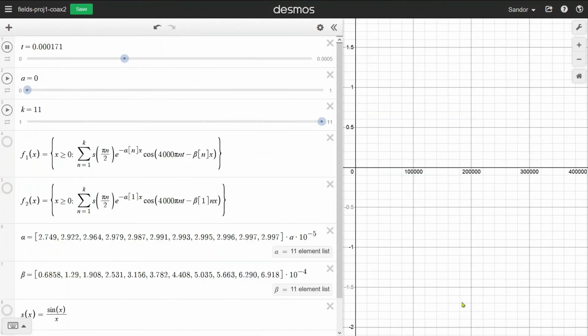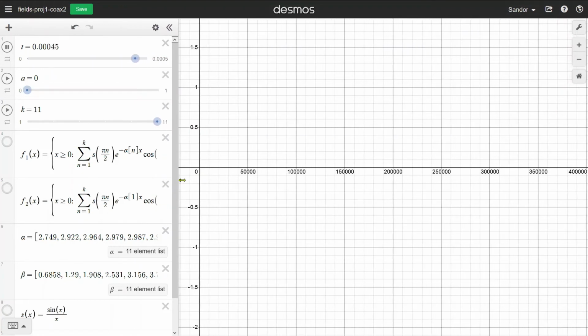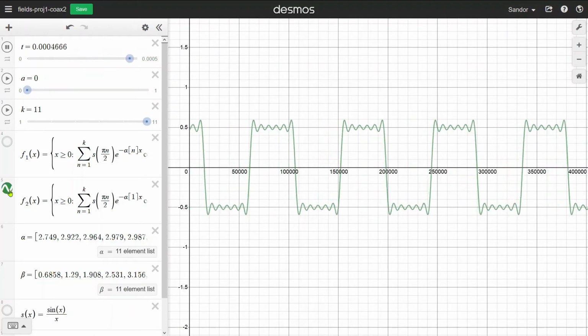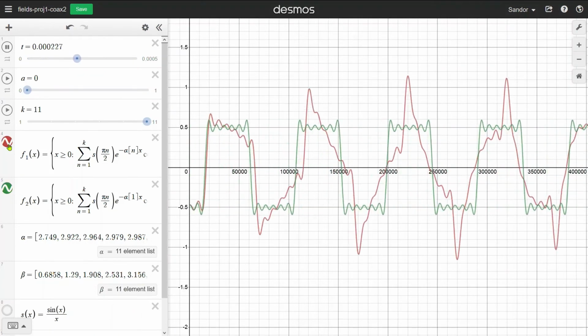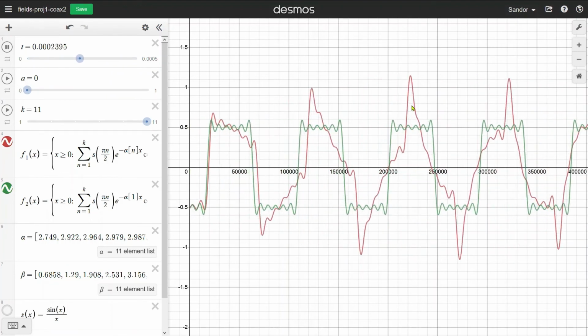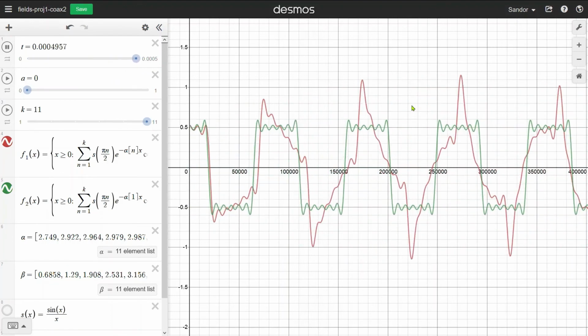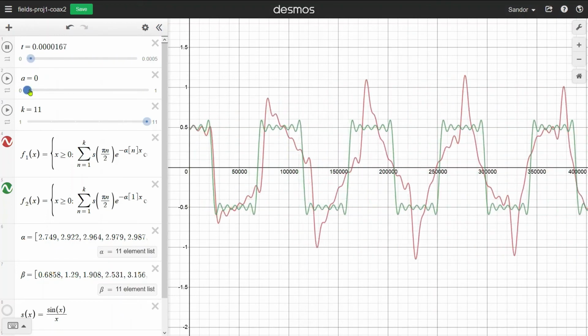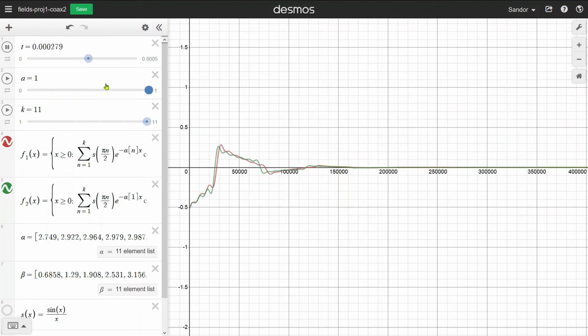The same can be seen for this 2 kHz square wave approximated by the first 6 non-zero terms of its Fourier series. Let's assume there's no attenuation for the moment. Here's what we should see, and here's what we actually see. Notice how the general high to low pattern of the pulses remains the same, but the higher frequency oscillations on top of them distort their shape. This is also visible with attenuation turned on.